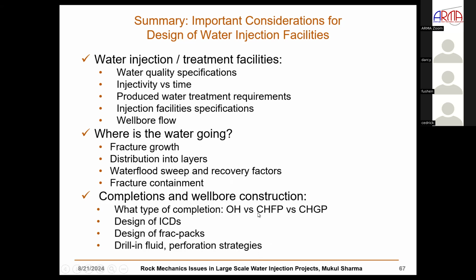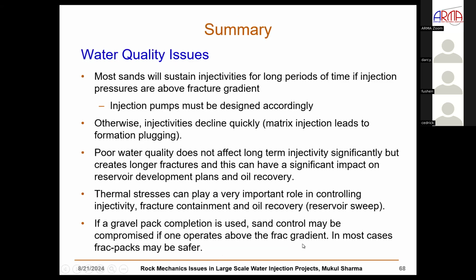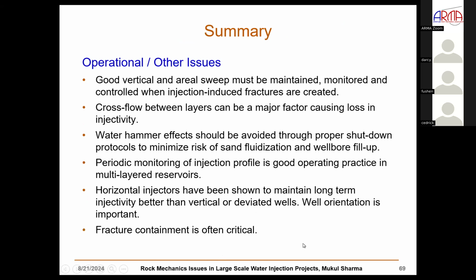And then, of course, it has implications for what type of completions: open hole, cased hole frac pack, cased hole gravel pack. Do we use ICDs? How do you design the ICDs, inflow control devices, and so on? It also has, I didn't talk about this, implications for drill-in fluids and perforation strategies. How do you place your perforations in vertical wells and horizontal wells, and so on?